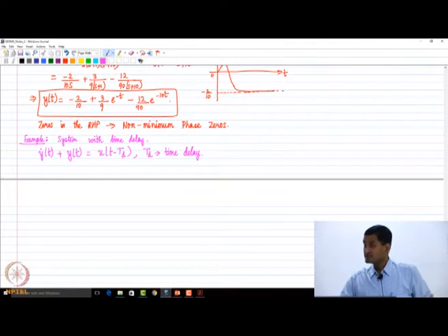Yes, we do. Suppose I want to push this desk. The force which I am applying is my input, and the displacement of the desk is the output. Will the desk start moving instantaneously? No, right? Why not? Exactly, you have to overcome static friction in the region of contact between the desk legs and the surface.